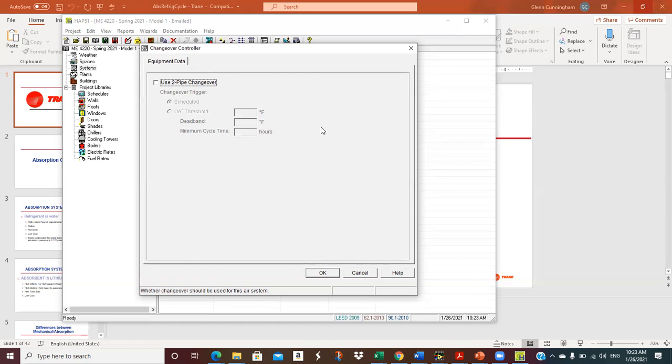Now, in this day and time, we can do all this with computer controls. If you have the building automation system, you can fire the boiler, fire the chiller, but you've got to be a little careful because you've got one coil, one distribution loop. Let's say we've been heating because it was real cold at night, so I've got a distribution loop that's 120 degrees.